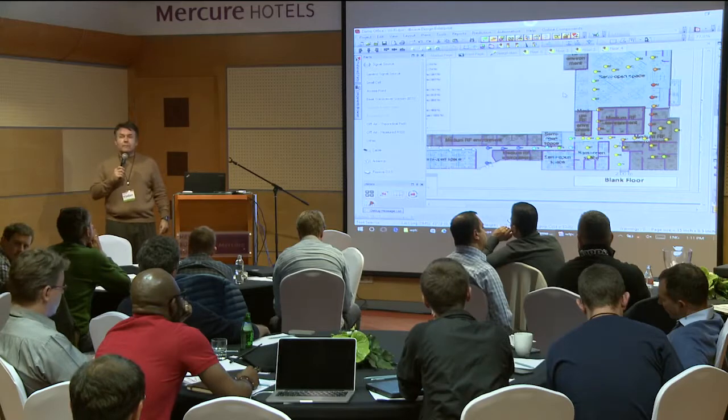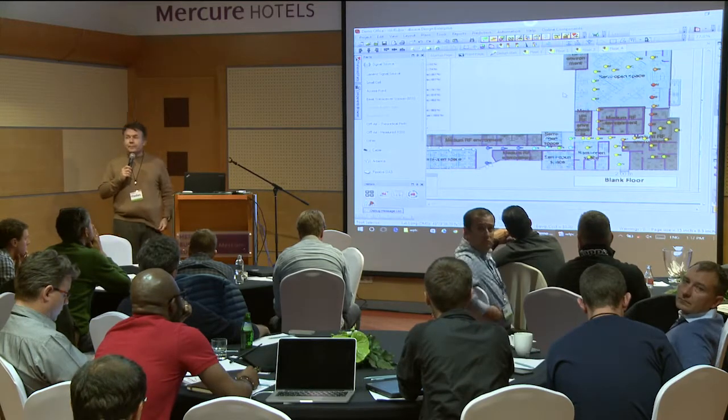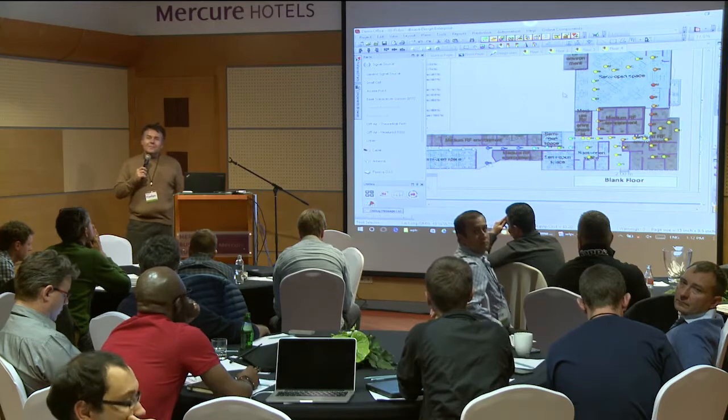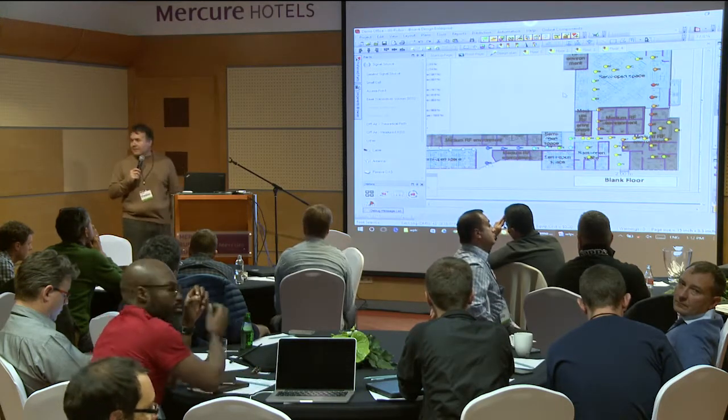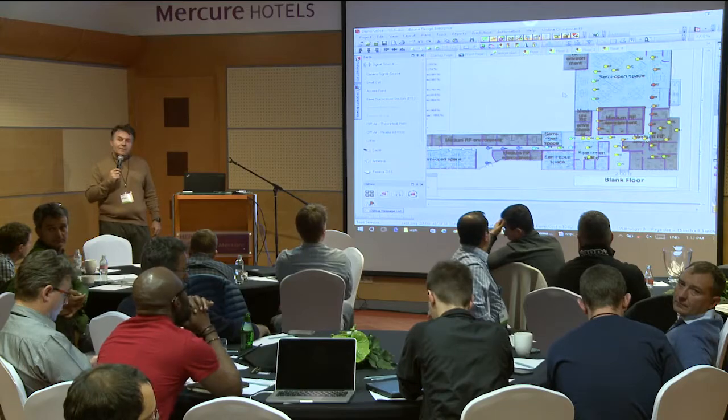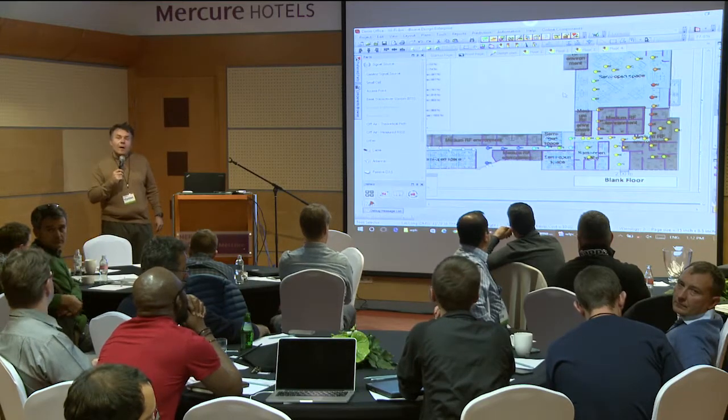Yeah, I have a question about that too. I heard from Twitter that if you do a survey, it is possible to validate the building model if you have a building model. Is that true? Okay, so are you talking about RF calibration? Yeah, you may call it this way. Okay, yes, we do have RF calibration. Basically what you would do is collect the CW data throughout the building, and then you can use that to calibrate your RF fast ray tracing propagation model.